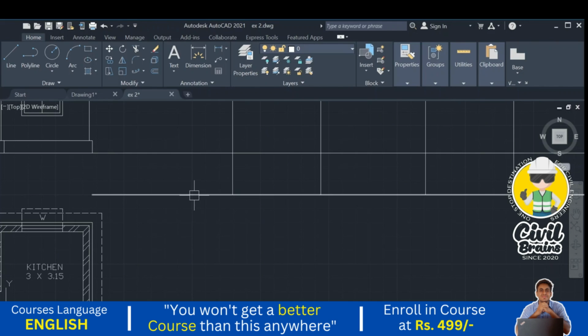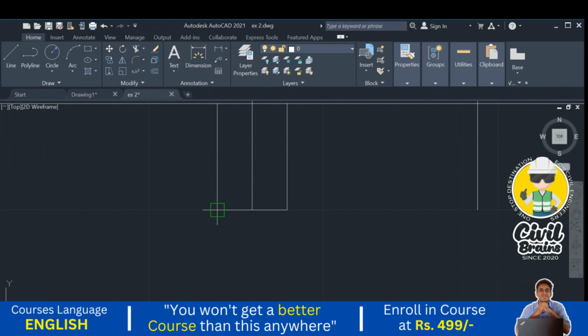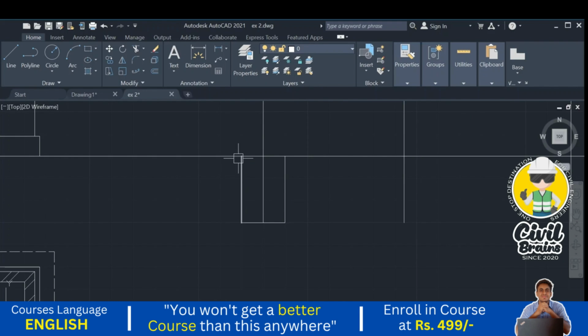So depth of the foundation we have marked. Width of the foundation, offset 1 meter we are taking, that is 0.5 and 0.5, correct. I just trim the extra part. Let's trim this one. We don't want all those things. So depth of the foundation is 1.5 and width of the foundation is 1 meter. Correct. So this much excavation we have done.